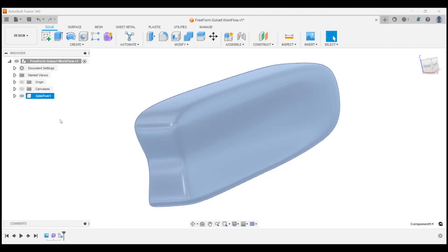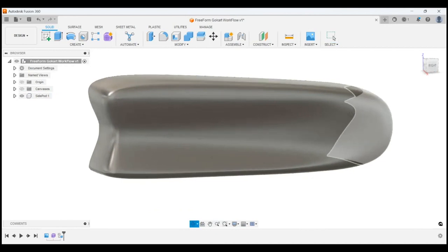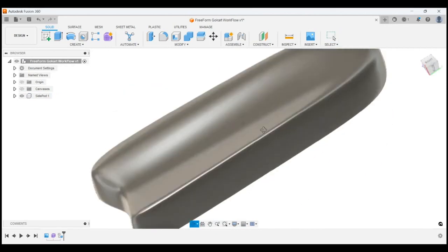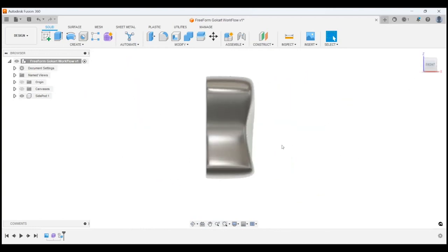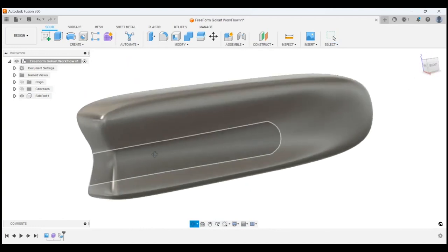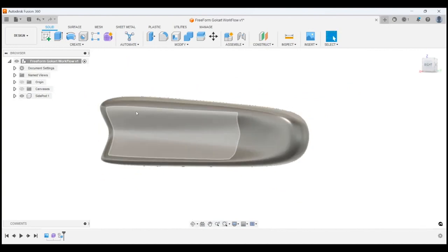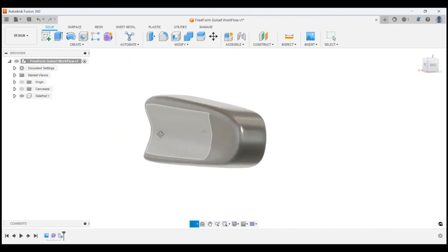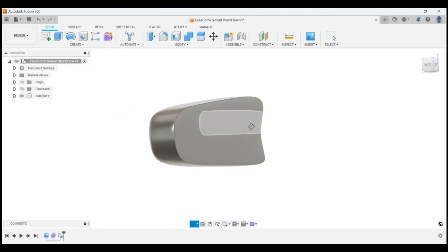Now, in last year's WorldSkills competition, obviously they wanted us to make the sidepod, but it actually had to attach to the go-kart. So whilst this isn't freeform, I just want to show you how you might go about doing extrusions through freeform and interfacing with other objects. Now, obviously this face is going to be difficult to work with because it's so curved, as are these faces in the front here, but this face is flat in this case.